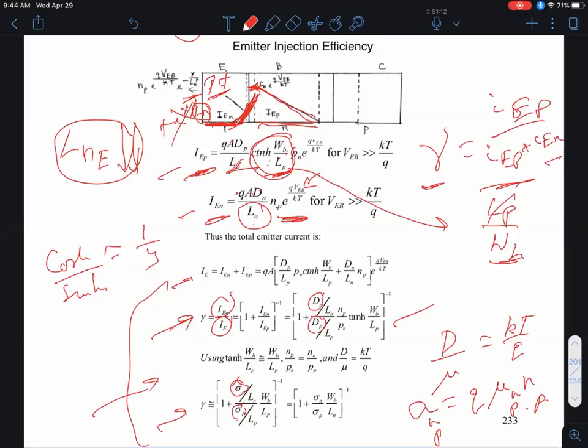So how could I change the problem? Well, before I do that, if I have this assumption now for the gamma, can anyone tell me what I have by default assumed for the base transport factor B? Anyone? Don't confuse this B with the base, by the way. Okay, that's base. That's my base transport factor. If I have a straight line, as shown over here, what value of B am I getting?